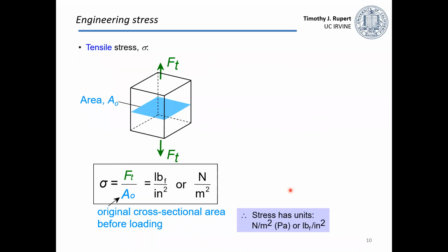So before we go on any further, what we need to do is define some of these terms I've mentioned in passing: stress and strain. So stress is just a way of normalizing force to remove the geometry of the sample size you're talking about. We'll start with the simplest one to visualize. This is a tensile stress. So we're pulling on our sample up and down in this case. We're going to take that force that we're applying and we're going to normalize it by the cross-sectional area.